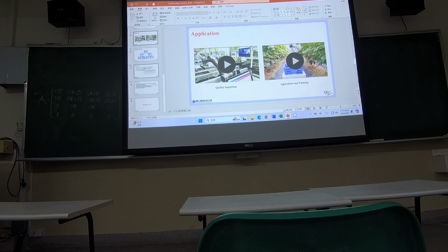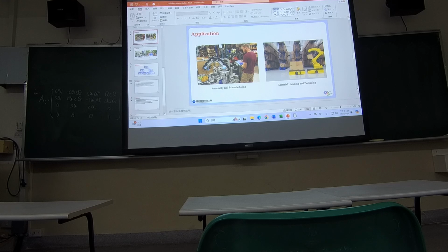As you have also shown in the figure, the main difference is that the joints of the cobots need torque sensors, so they can sense the torque from the environment. That's how they do the control strategies. And another very good question: if you know that you need this kind of control strategy, like impedance control, is this an open loop or a closed loop control system? You can just choose one.